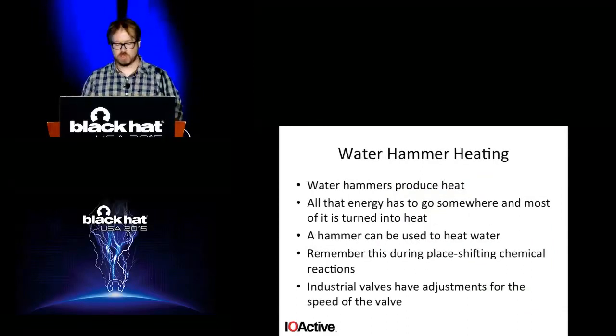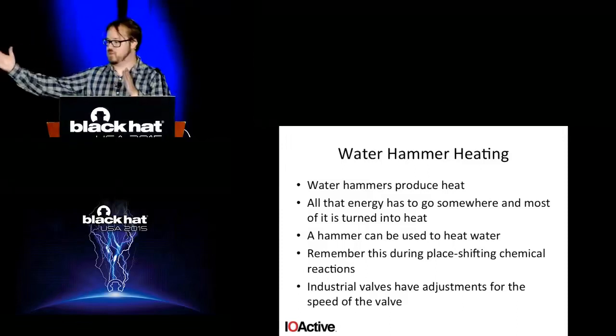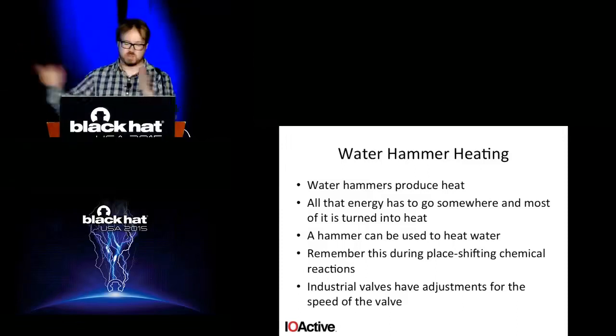So one of the things that you can get about water hammers is you have this big volume of water moving through the pipe, and it comes to a sudden stop. That's a lot of energy. The energy there is almost always converted to heat. So if you go look to where a water hammer has actually destroyed a piping structure inside of a factory, one of the things that's almost always observed is that the pipes are hot to the touch. So if you open the pipe and let the water slide through and you slam it and the water slams to a halt, it's going to turn most of that energy into heat.